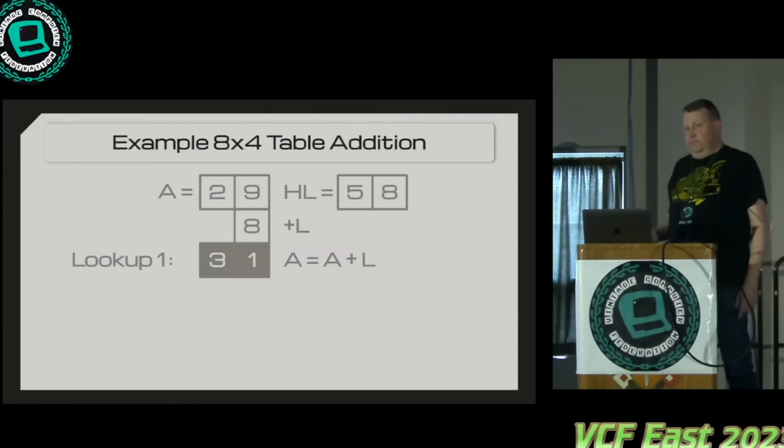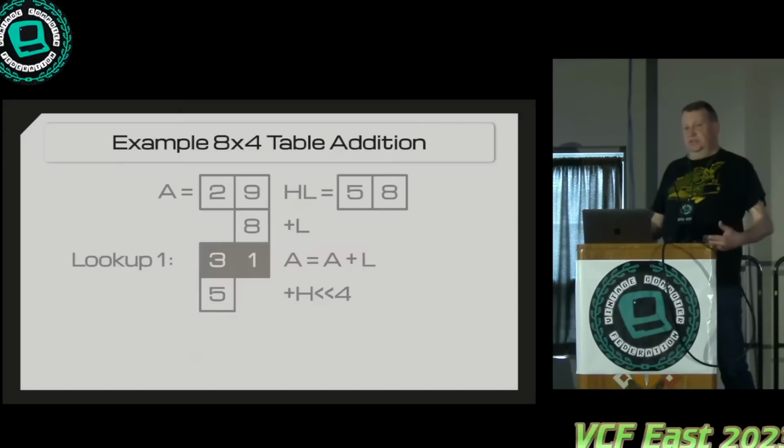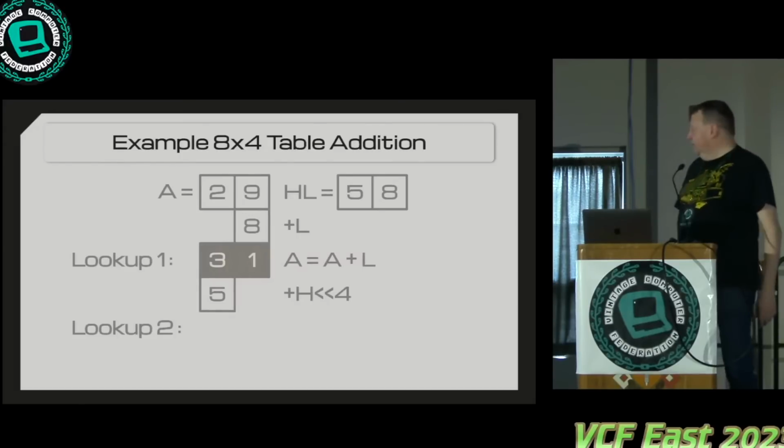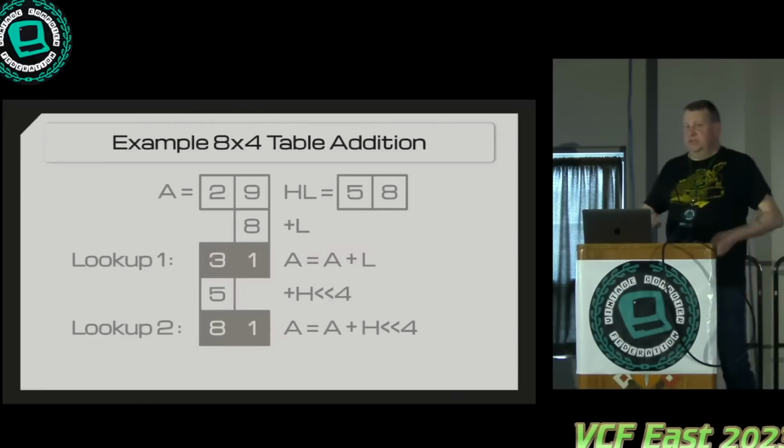And then you just recycle that and do another operation using a different table which treats the next nibble as if it was shifted up by 4. And then you get to this sort of 8-1 result. That's actually not too complicated to do, so it's a good trade-off. So in that 64K of ROM, I can actually put 8 operations, but it still does that 2 cycle.